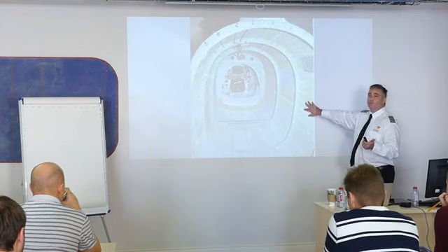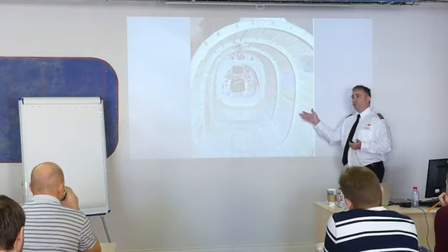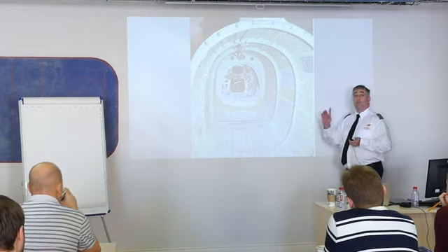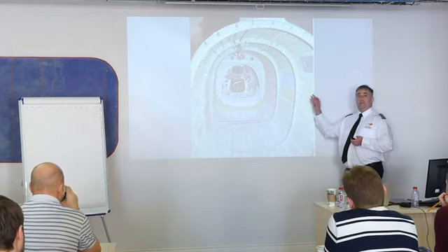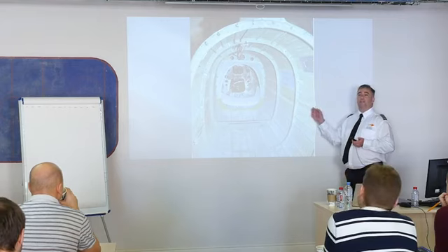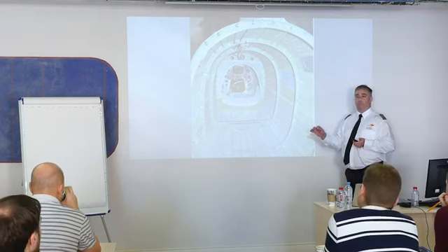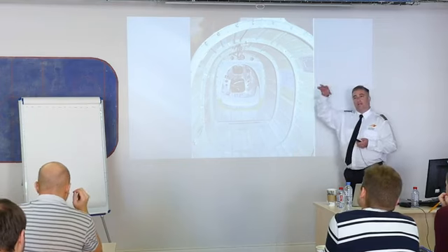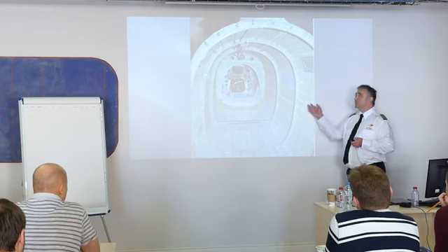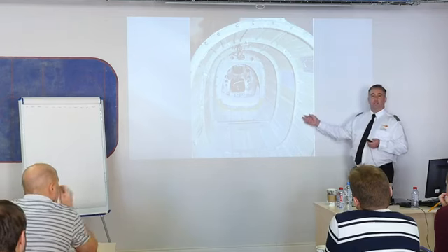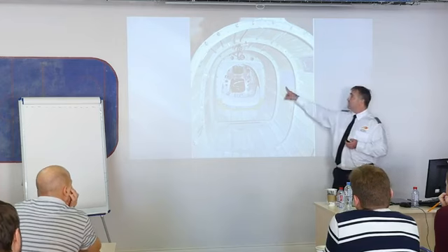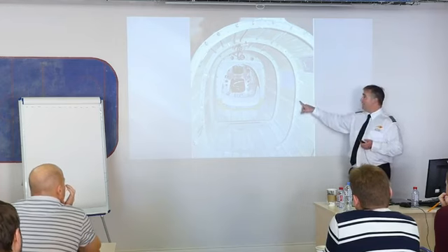A little bit of extra weight, it's all sheet metal, so either aluminum or sheet metal, so still very lightweight. But each one of these has a little bit of extra weight, and this is what's called a semi-monocoque design airplane, which, if you remember when we first went through the key terms, they had monocoque and semi-monocoque. So this is called a semi-monocoque airplane. If it were a monocoque airplane, it would not have these longerons and not have the stringers.